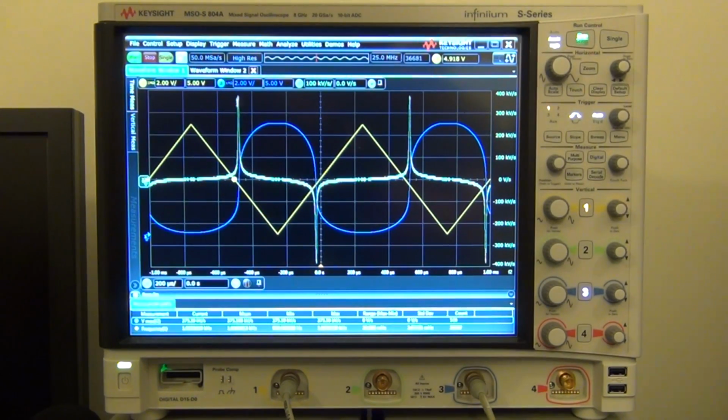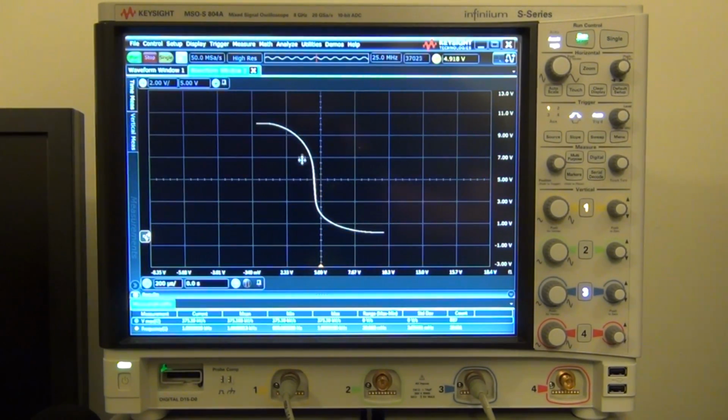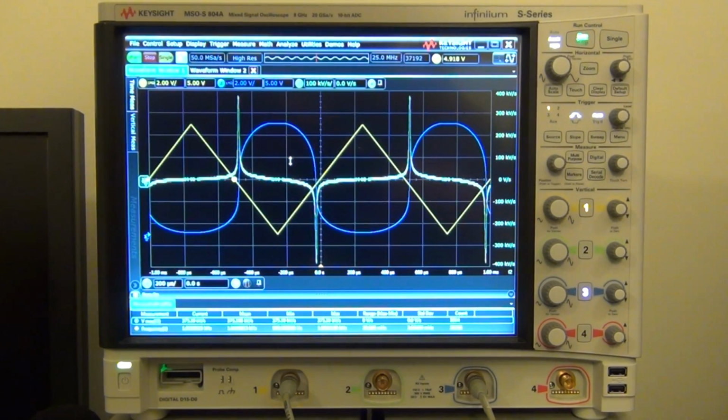The function that calculates the derivative has peaks, so you can see as a positive peak here the gain is positive, as a negative peak here the gain is negative, and so on and on. And by this we can find out what the slope is. And why would we bother with that? Well, if you want to find a gain of this, you have to calculate the slope of this curve right here. But that's difficult to calculate in this form, so this is another way of doing that.